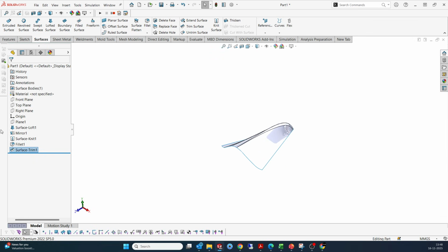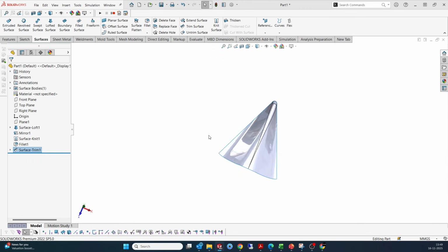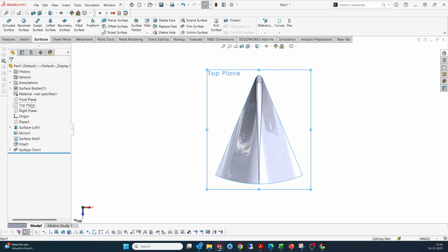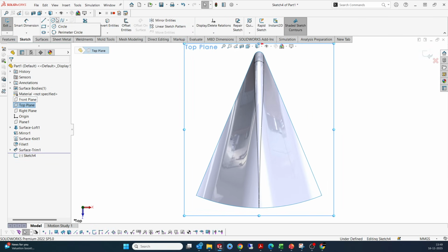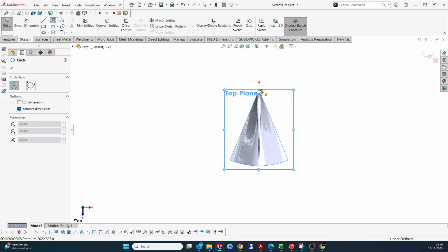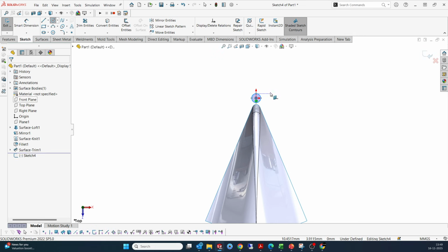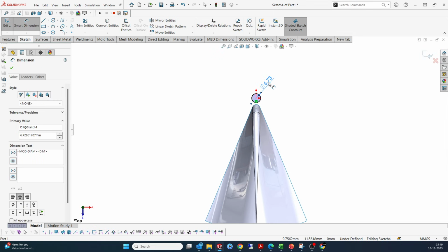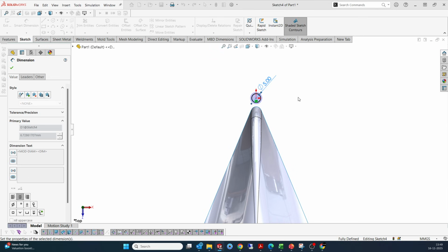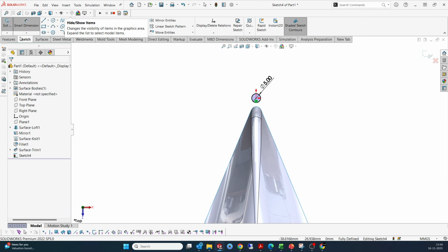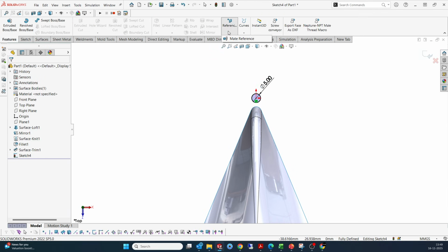Cool. Now I have to make that circular completely, but before that I just want to create another profile, which we have to make more of a skeleton, as you have seen in the thumbnail. For that I'm going to explain another tricky way. Select the top line, go for the center, somewhere around 5 could be fine. Yeah, that's what I've used before. We'll use the same 5 over here, and a circle.